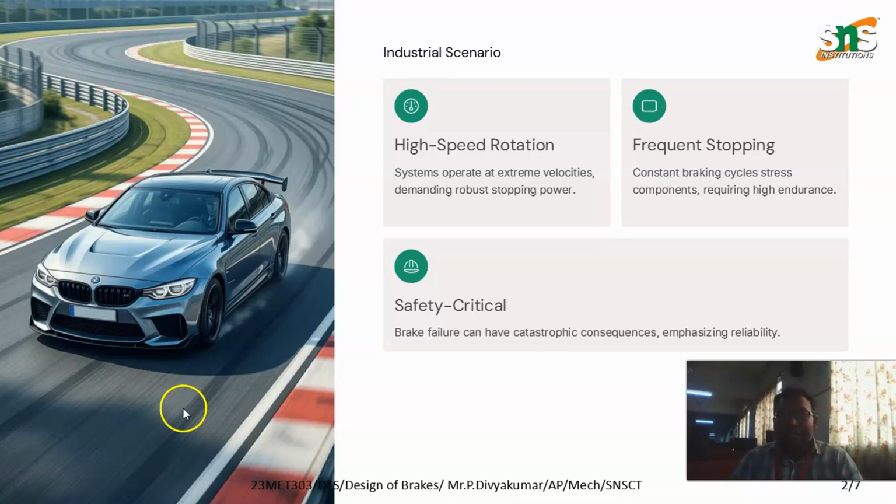The principle of braking is: brakes work on the principle of friction. When a stationary brake lining comes into contact with the rotating drum or disc, frictional force is produced. This friction opposes motion and converts kinetic energy into heat energy.